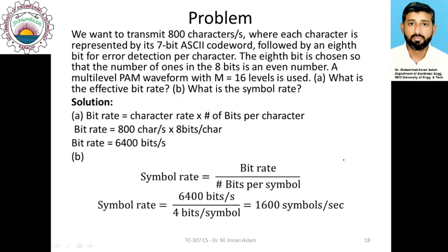Then we use an encoder to transform the quantized levels to a specific bit stream, and then pulse code modulation is used to transform this bit stream into pulses or waveforms so that it can transmit the signal.